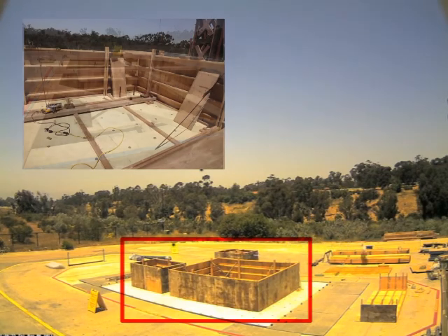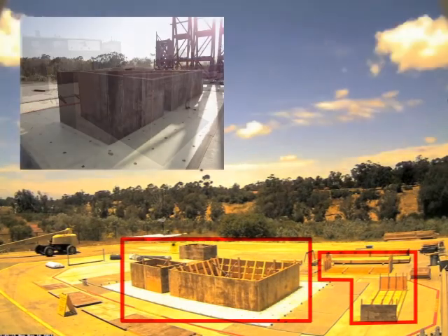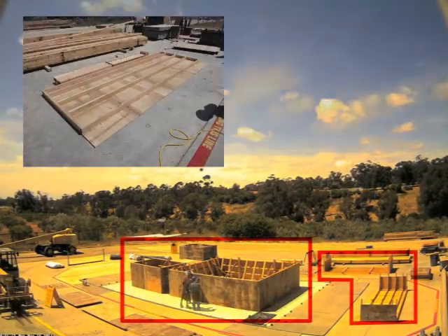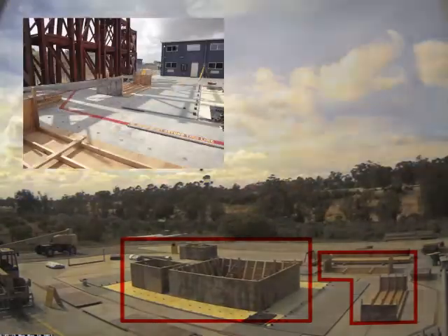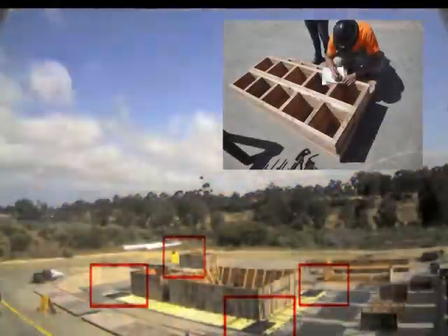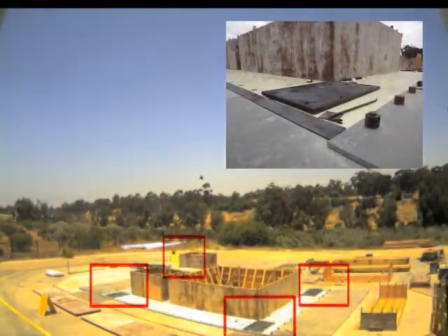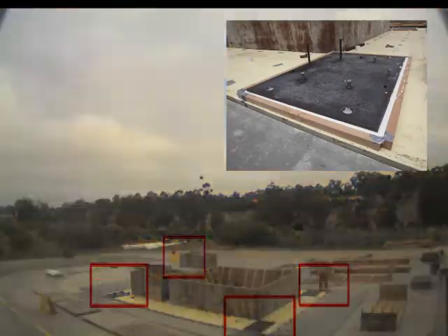In this particular case, the interior formwork segment was installed first. After completion of the interior formwork, the exterior formwork of the foundation is constructed. Unlike traditional building construction, box elements were fabricated at each edge of the foundation to block the concrete from filling the space where base isolators would eventually be installed.